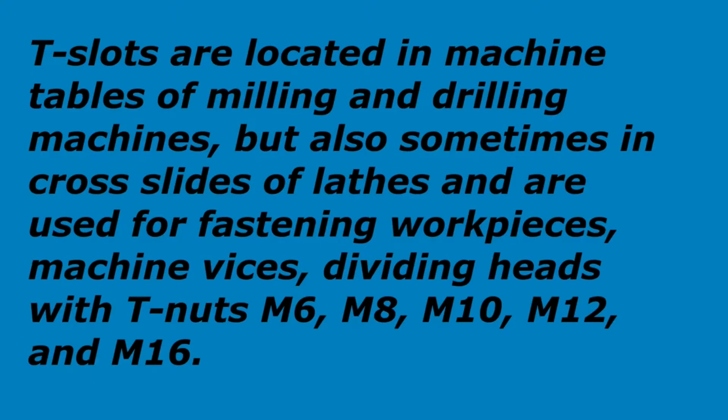T-slots are located in machine tables of milling and drilling machines, but also sometimes in cross slides of lathes, and are used for fastening workpieces, machine vices, and dividing heads with T-nuts M6, M8, M10, M12, and M16.